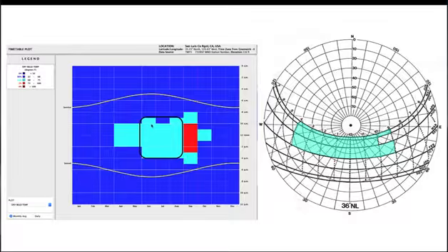Looking at the summer sun path chart, starting in June all the way till August, from 9 approximately, 10 o'clock for July, to 4, we're going to transfer these blue times, which people are comfortable, onto the sun path chart. So I say here's June, I'm going to look below the line, go to 9, shade in from 9 to 4, people are comfortable. Then I'm going to go to July, below the line, 10 o'clock to 4.